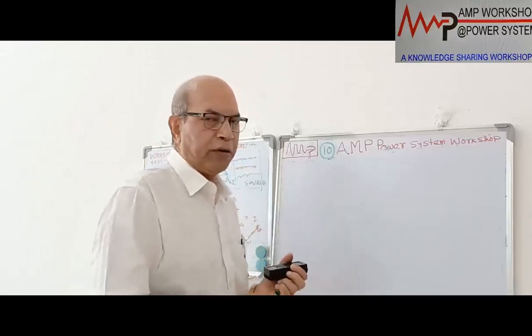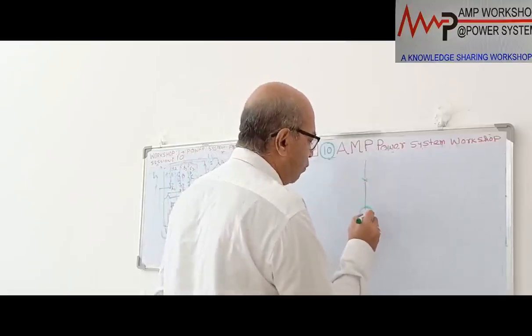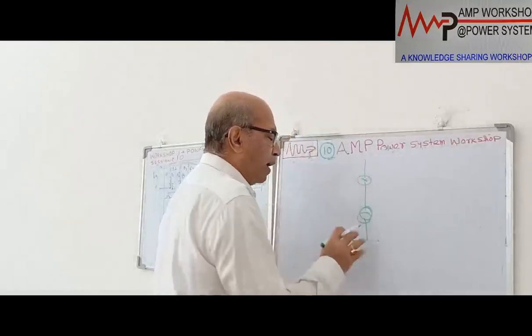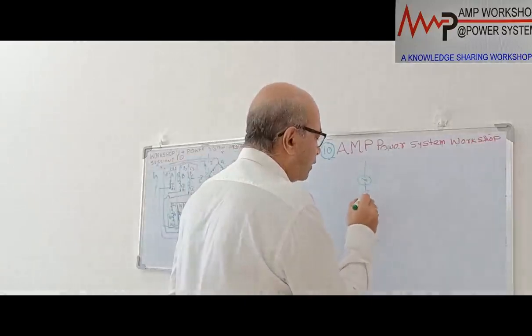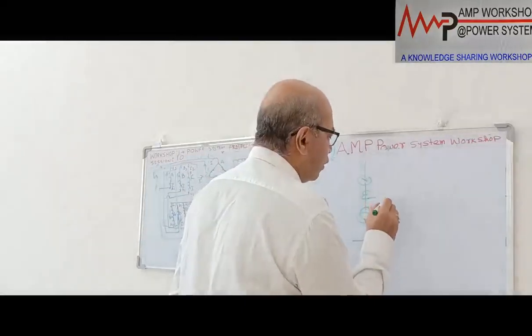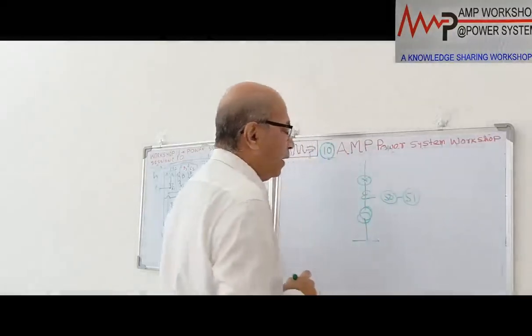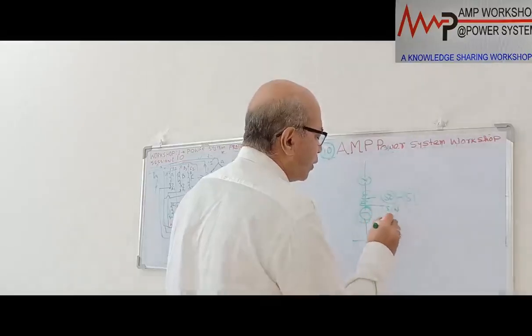For that, what we normally provide, as it is considered a transformer feeder, this is a transformer, actually one autotransformer you can say. This feeder we provide for its internal fault. We put two sets of CT. One set of CT we put over here with the instantaneous overcurrent and IDMT overcurrent protection. Another set of CT we provide for 51N protection.